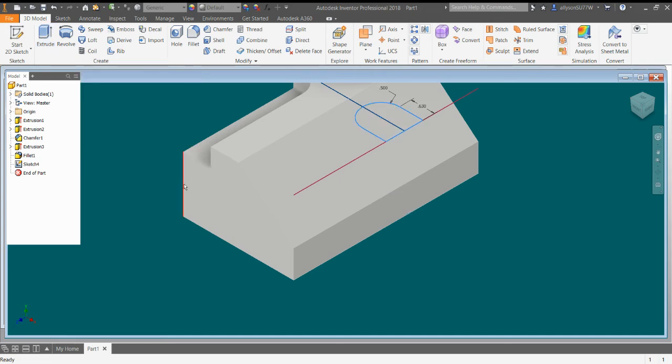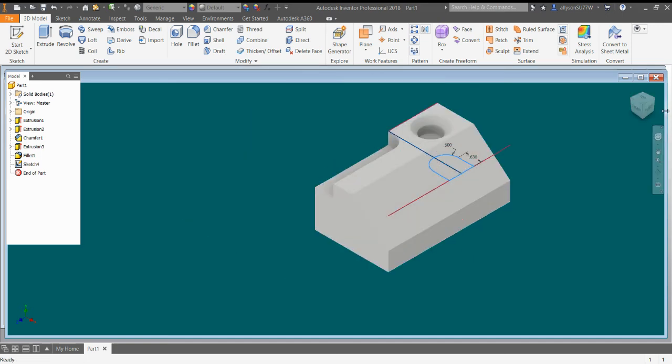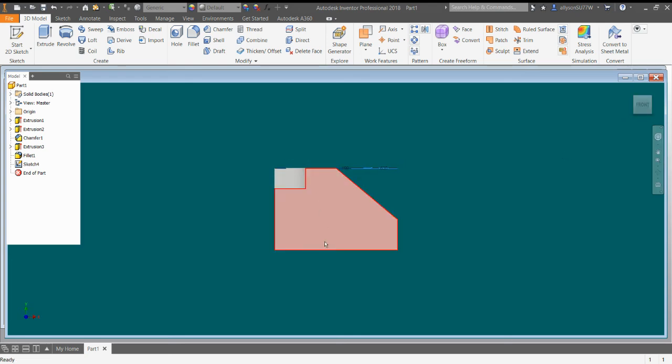We're in profile now, so we want to cut 2. This is not going to give us the option we want. So now is where I tell my kids that there's more than one way to do this. We know that when we made this part, the total length of this part here was 2 inches. And we know that this part here is 0.75. But we need to be able to cut to this line here. So if I did some math, if I have a distance of 2 inches and I have this part that is 0.75, I need to be able to cut 1.25. If I add 1.25 to 0.75, I'm going to get 2 inches. And that's where we want to go. We want to cut it to this section here.